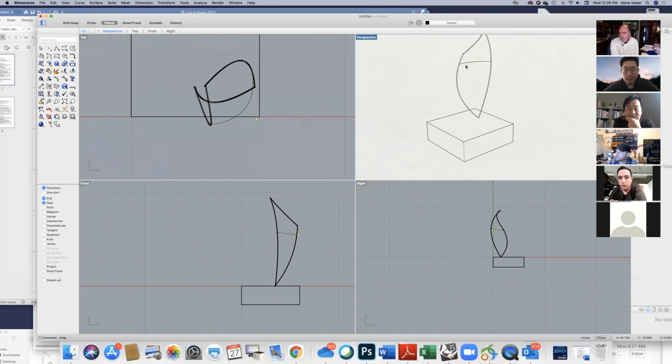And I would recommend that students do primarily 3-point arcs. If they want to try being a little more adventuresome, they can do 4-point arcs. The danger is you can end up with a non-planar arc. With 3-point, no matter what you do, it will be a planar arc, and they'll be able to print it out and bend the wire. With 4-point, it's possible to have 4 points that are not in the same plane. 3 points will always be in the same plane. And so that's why I recommend that students do it with 3-point.